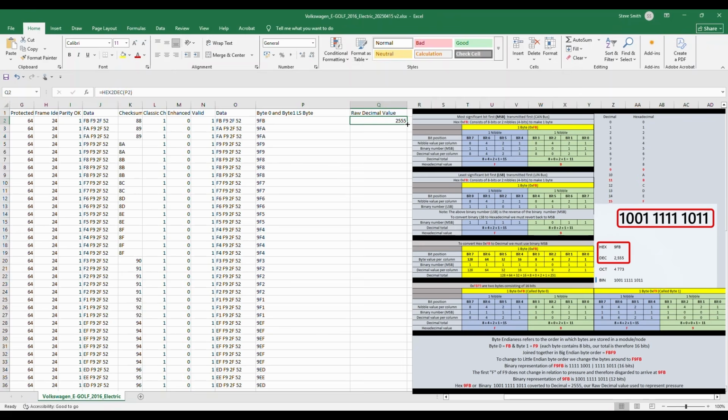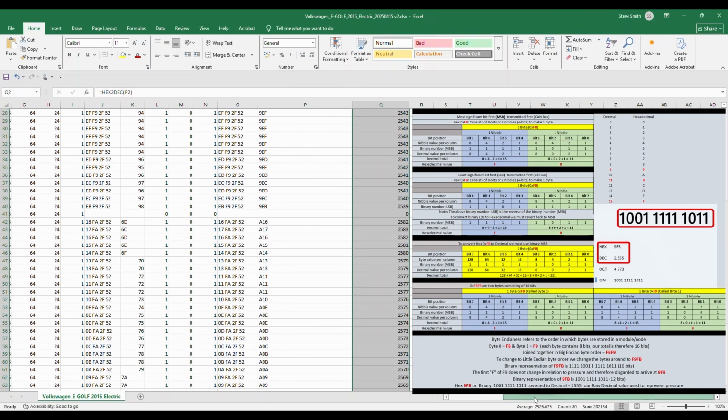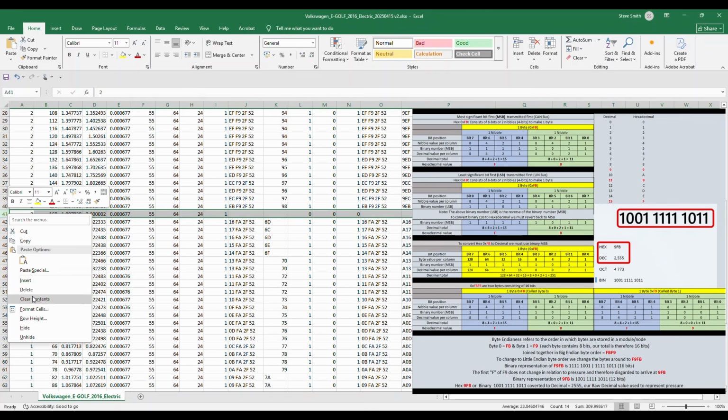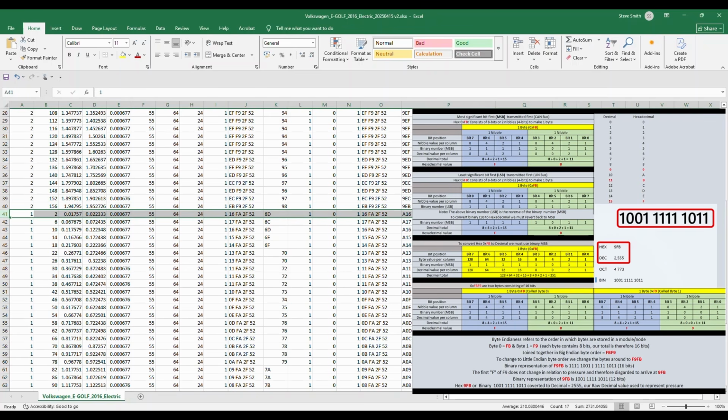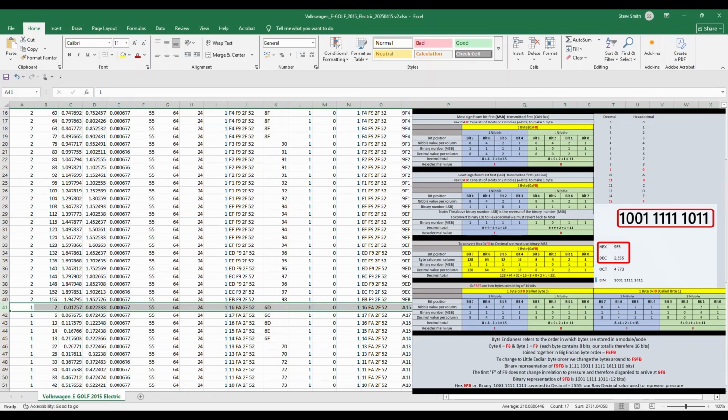Double click in here. That will apply that to all data. Now this is interesting. This column here, column 41, has come back as a 0, and it looks like it was on the cusp of going from buffer 1 to buffer 2. So we probably had half a packet there. So we will just delete that row, because that stops us having a crazy value in the graph.